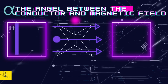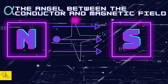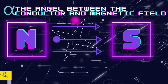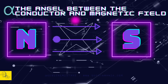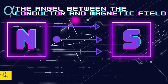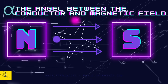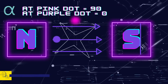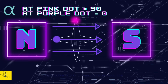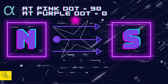Why? Because when the conductor and the magnetic field are perpendicular to each other, we are making the most voltage. So if we assume that alpha is the angle between the conductor and the magnetic field, then when the star is at the pink point, the conductor and the magnetic field are making 90 degrees angle.